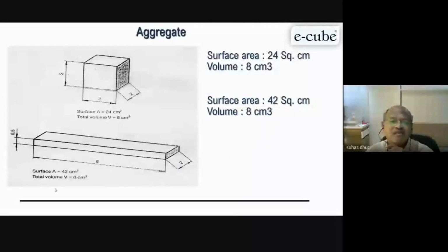Similarly, I was talking about flaky material. See, this is a flaky material, 20 mm here. Here is also 20 mm, 2 centimeter, but this is angular in shape. See the area here, and see the same material is flaky and elongated, flat and elongated. Slate-like material is coming from limestone, as I said earlier. So once the source changes, this area has increased. Now to coat this surface area, we require a different amount of paste content.